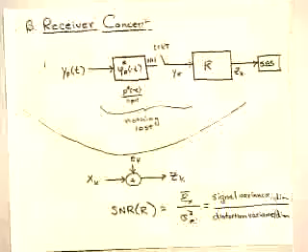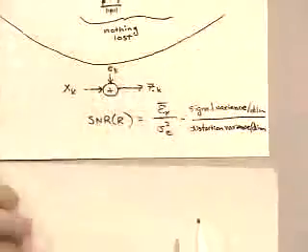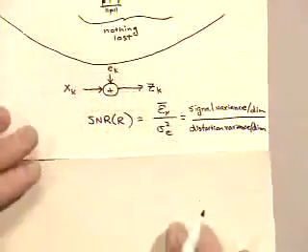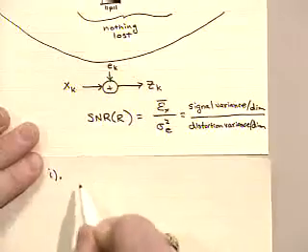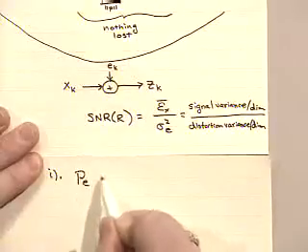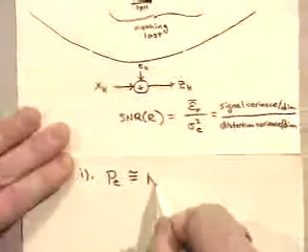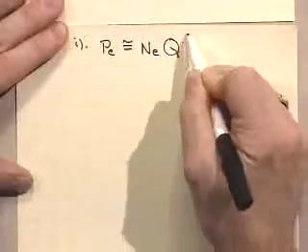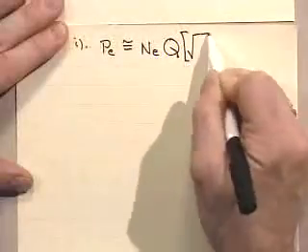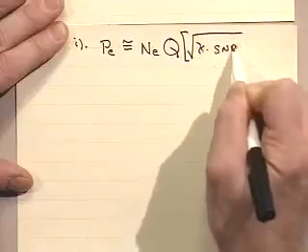And at that point, I say, well, hopefully since a lot of things are still getting added together here in this distortion, that's probably still close to Gaussian, and so I know I can approximate, may not be an upper bound anymore, my probability of error by the number of nearest neighbors times Q times some, let's call it kappa, times a signal-to-noise ratio.